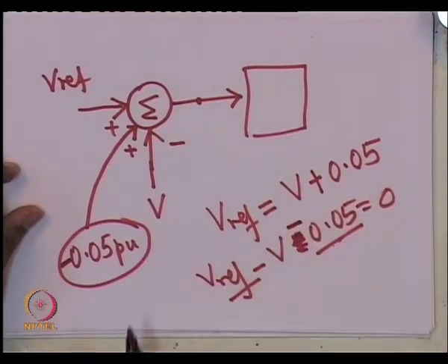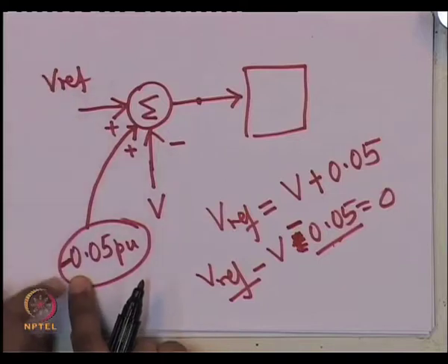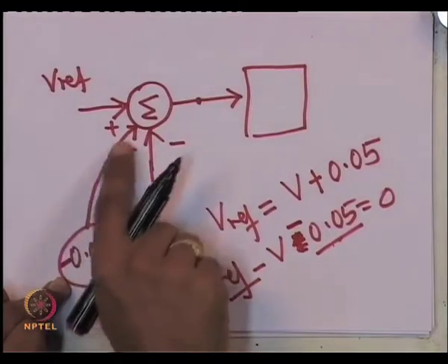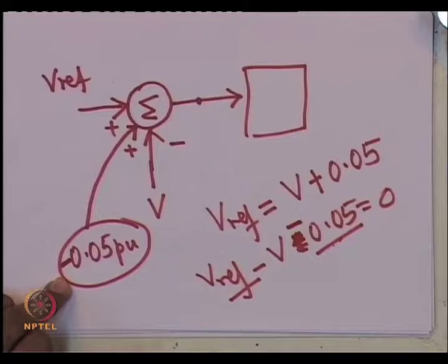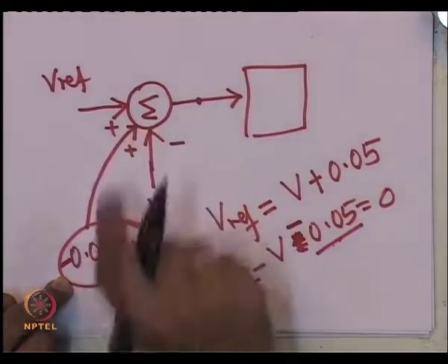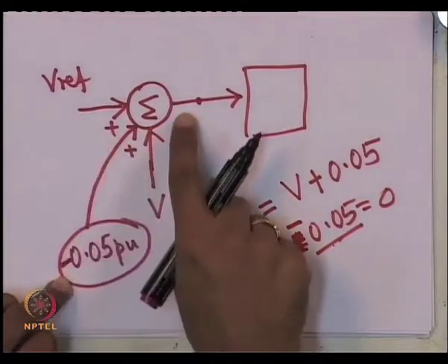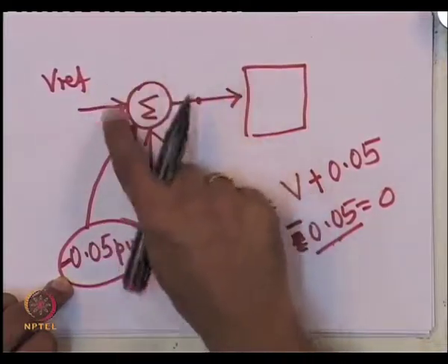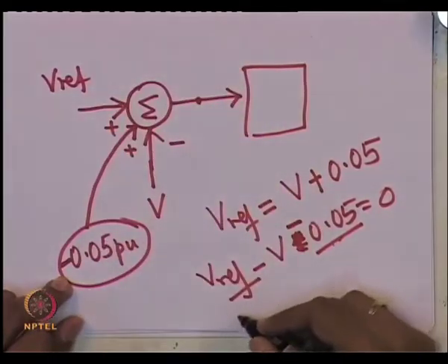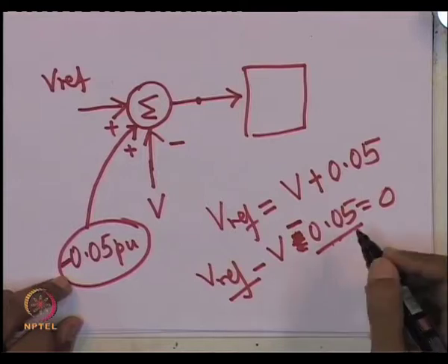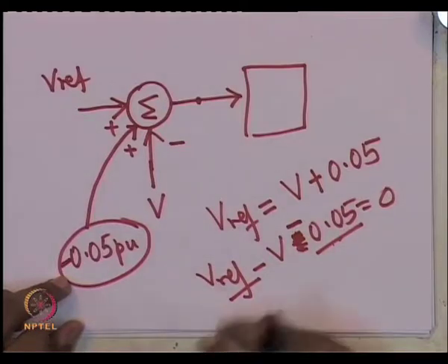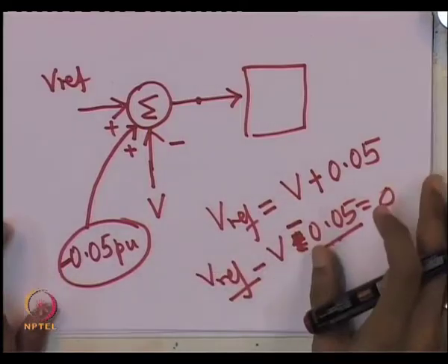this becomes minus, you may adjust this Vref by an additional signal which adds on to this summing point. So, I may add on minus 0.05, so I augment what comes out of this summer. So, finally, V will not be equal to Vref, but slightly less than Vref. Okay. So, this is what effectively limiting functions does.